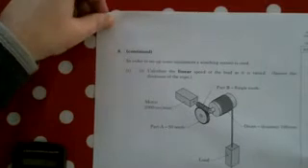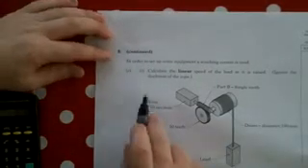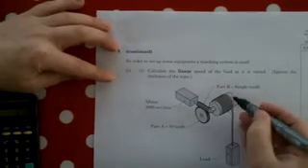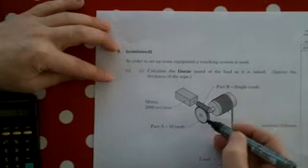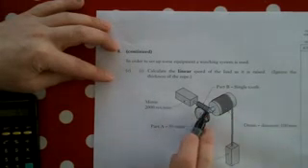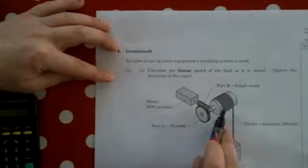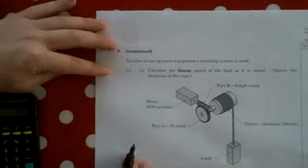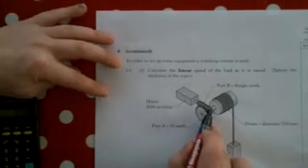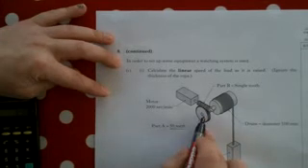It says, in order to set up some equipment, a winching system is used. Calculate the linear speed of the load. Well, here's the load being lifted by the winding drum, and the winding drum's being turned by a motor, and the motor is transferred through a worm and wheel. So we need to work out the speed as it reduces. So the first thing we need to do, a worm has only got one tooth, so we've already got a 50 tooth to 1 tooth reduction.